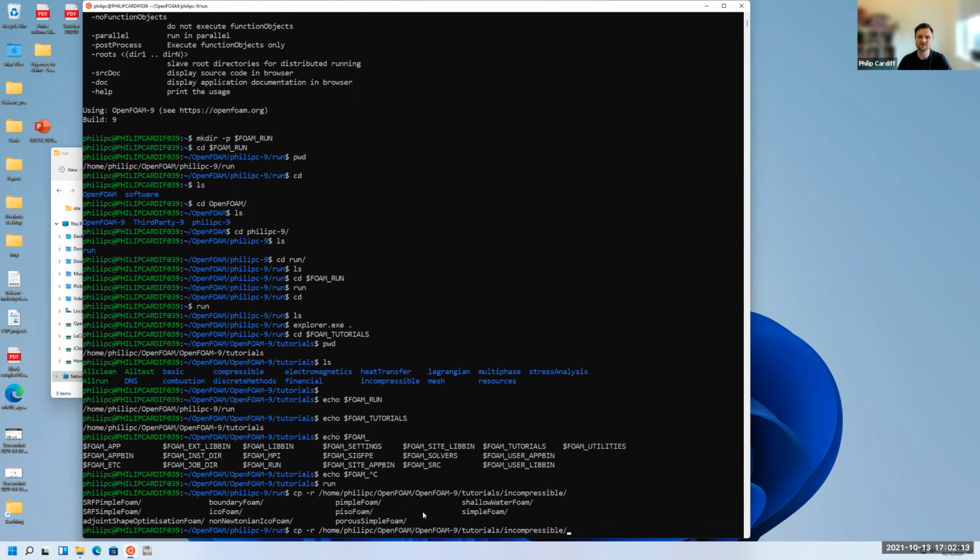In OpenFOAM, there isn't just an OpenFOAM application. It's not like Fluent or Abaqus, but instead there are many different applications or executables. If you want to solve incompressible flow, there are a bunch of solvers you may choose from, whether it's going to be steady state or transient. In Fluent, we could choose a coupled algorithm or a SIMPLE algorithm or PISO algorithm to solve the governing equations. But in OpenFOAM, they're all different solvers. So you'll have simpleFoam, pisoFoam, or a coupled solver foam.